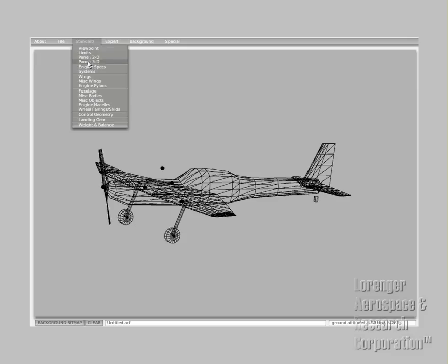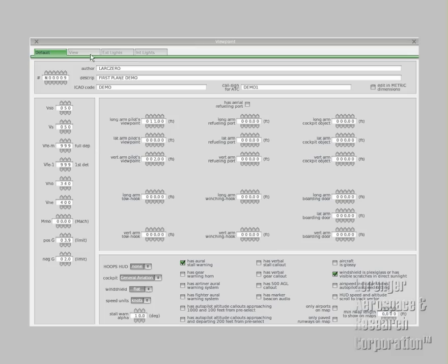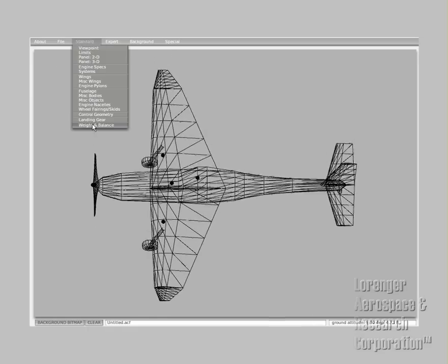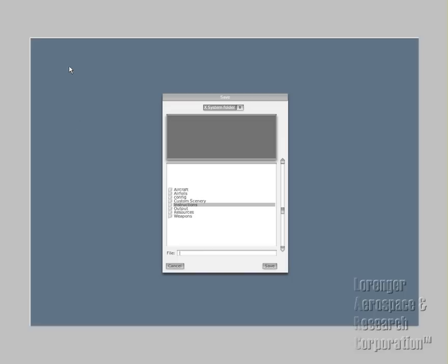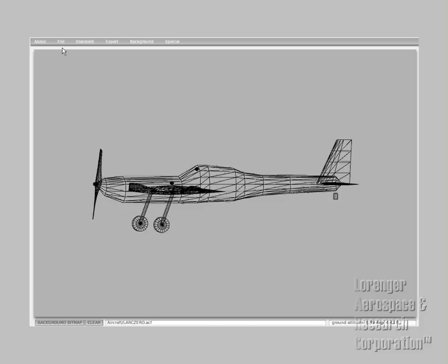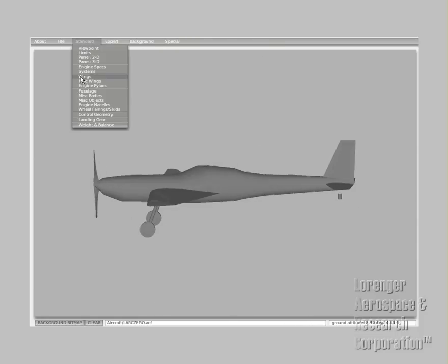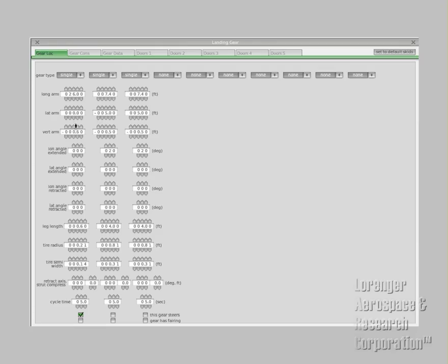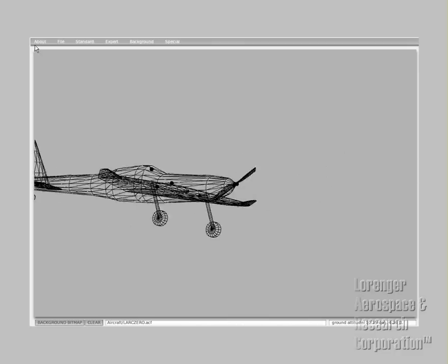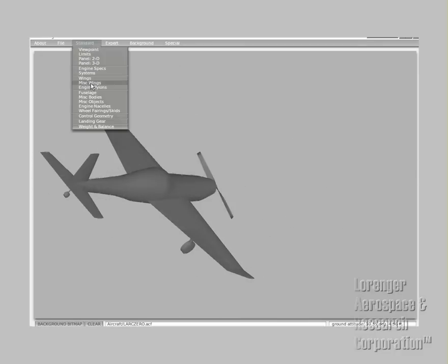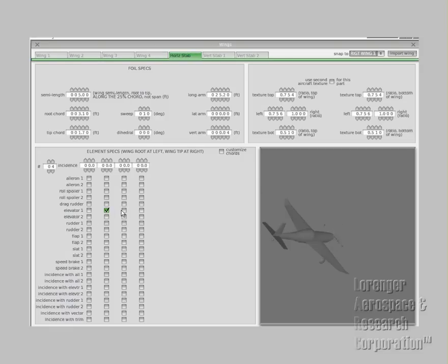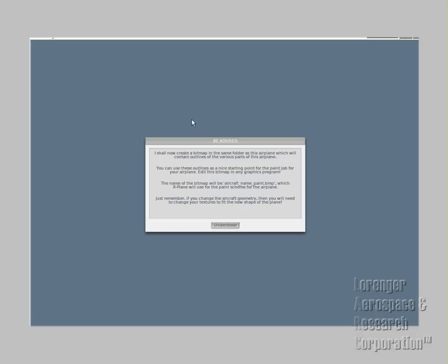Okay, center of gravity. Make sure you put this near your mean aerodynamic center, MAC. That's typically 25% of chord. The true aspect ratio. It's really hard to do that with X-Plane because X-Plane actually calculates engine weights. And if you get really funky with weapons and weapon objects that have their own weights, you can really throw the CG off. Also by adding fuel in the wings, which are a little further aft, but more on that later. But the goal here is to have a little bit more weight towards the front of the center of pressure. It's been a while. My aerodynamics are a little slipping.